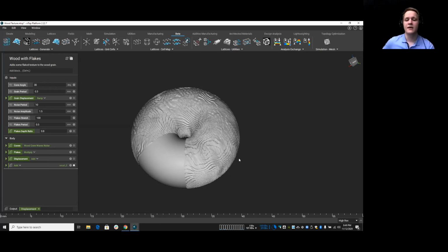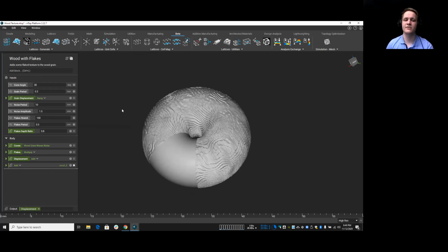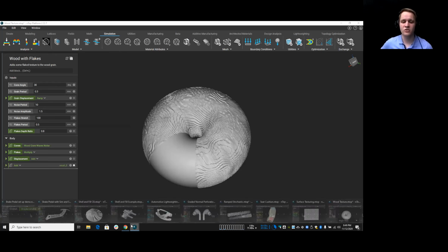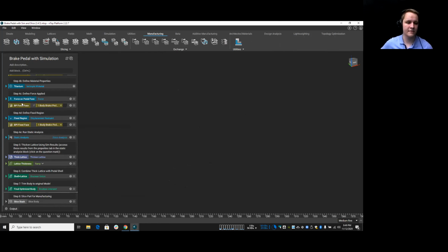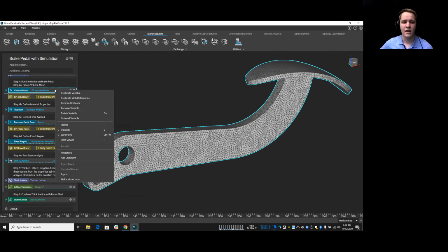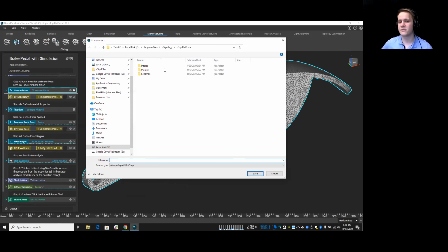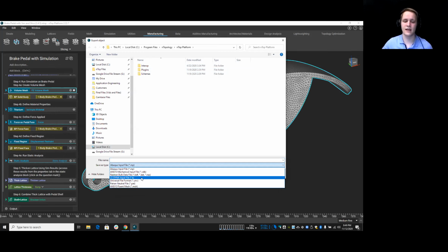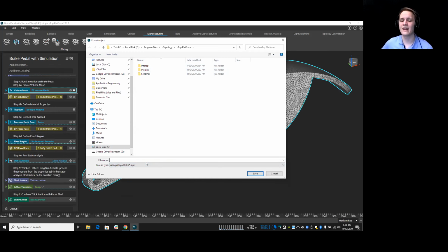One thing I'll say is you don't have to do your stress analysis or thermal analysis inside of NTop platform. Our solver is for linear steady state analyses. That means if you have very large deformations or anything non-linear in that sense, what you'll need to do is take your volumetric mesh, and let me back up a bit. So if we have this volume mesh and we want to take it to do a more complex simulation, we can actually export it to Abaqus, ANSYS, Nastran, LS-DYNA, or universal format, so we can get it into pretty much any other complex solver that you need to do.